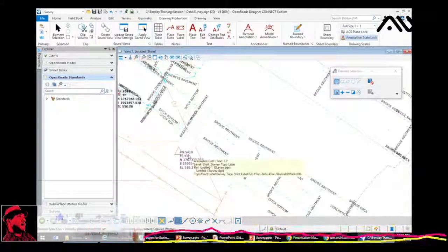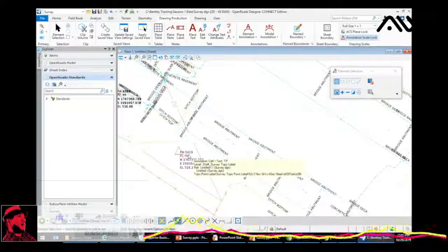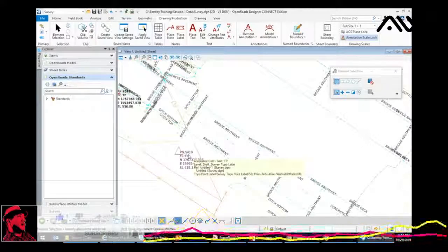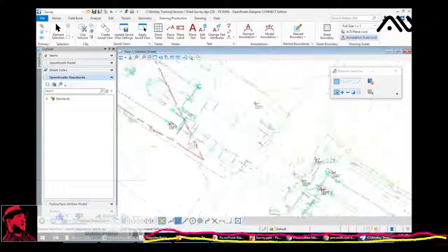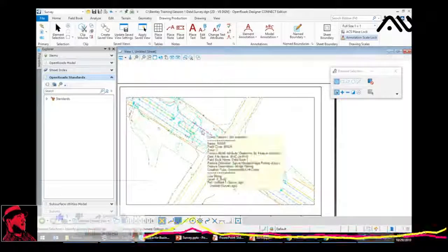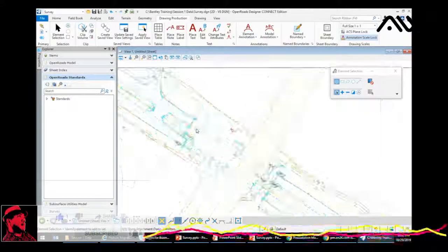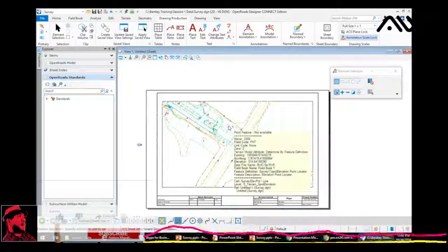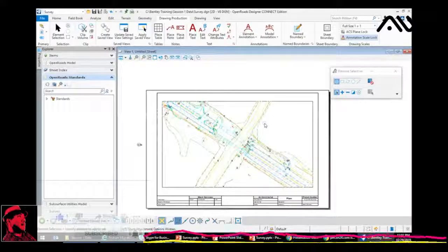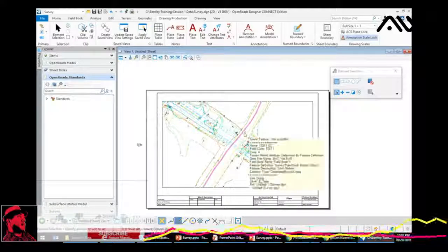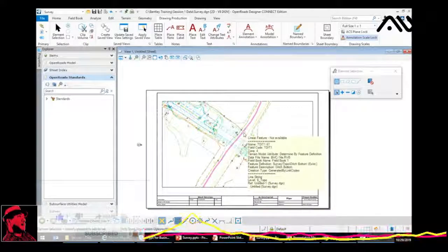So that is almost start to finish. We brought in raw data. We corrected the 2D planimetrics. We fixed up the 3D terrain. We got our terrain out to a separate file so we can send to design. And then we did a little bit of plans production, just using the feature definitions that were already created on our elements. And finally created our plan sheet here that we can send out to plotting. All right, so that is kind of real fast through the basic survey workflow.